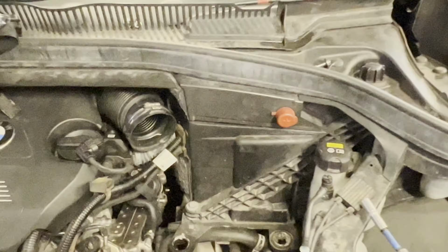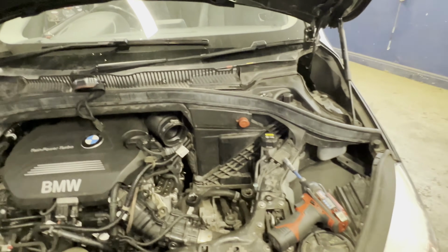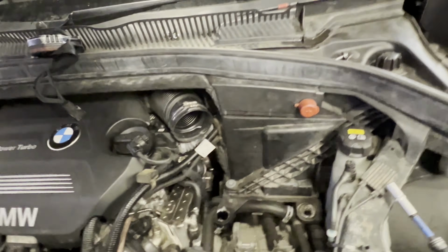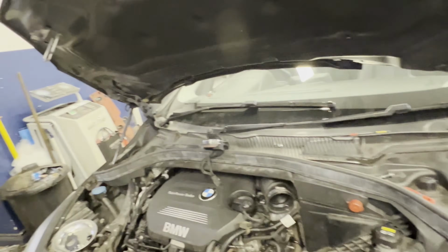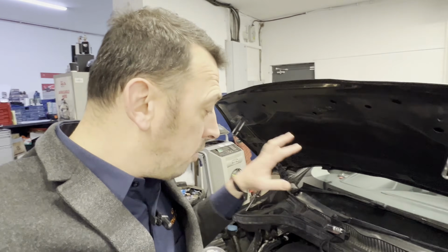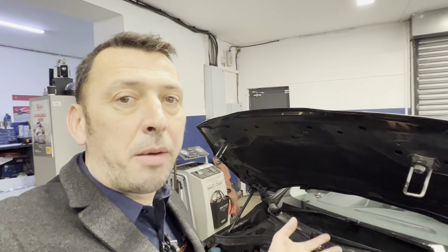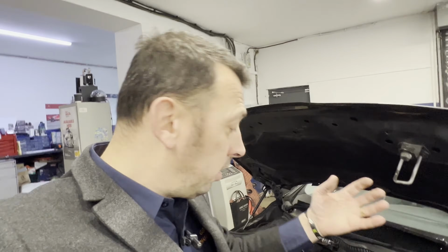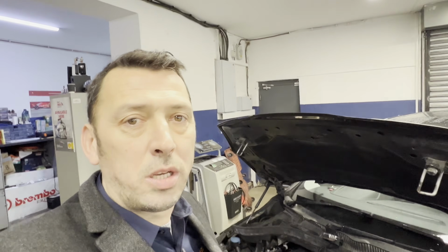So we stripped apart the ECU and cleaned it, and all we were left with was a fault related to the MAF intake air leakage. We had that fault at the beginning of the video, and we couldn't clear it until we used the dealer tool to perform the air mass test. Interestingly enough, it passed the test even with the blanking on the EGR. That's quite strange, but it managed to pass. Probably it didn't test the EGR in full operation, but it passed the test on the MAF sensor and deleted the fault.